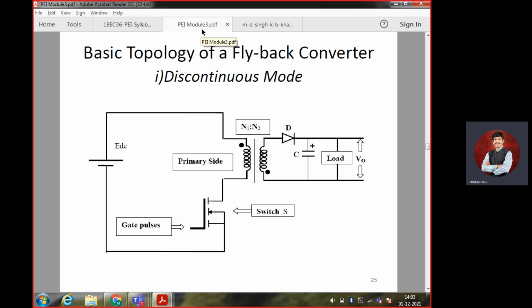See what exactly this resembles. It is a simple rectifier only, a rectifier circuit. This entire thing is a rectifier circuit, what we have done in our lab. The transformer is having 220 volts AC, that will convert into step down AC, and the AC is being given to the diode. The diode gives a DC signal.